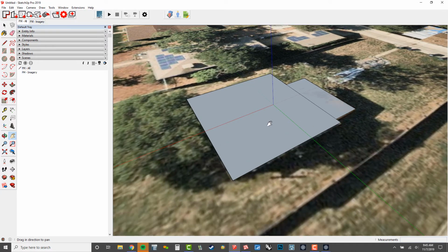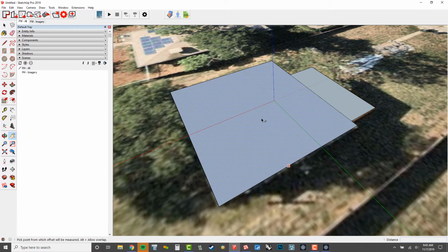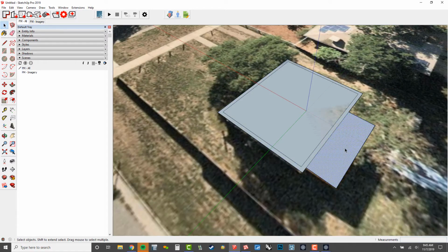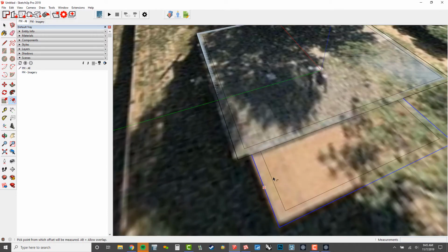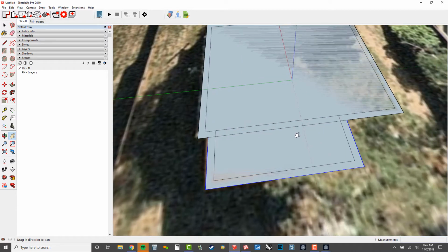All right, so as I said, there's like a 1 foot overhang there, soffit. So I'll just offset this by like 12 inches. And then I'm going to offset this one as well. We'll go with offset, and I can just double click, and that'll repeat the last offset. All right, and then these walls do in fact go back here. So I'll just kind of make that happen. And then as I said, I could offset again and say like 8 inches.